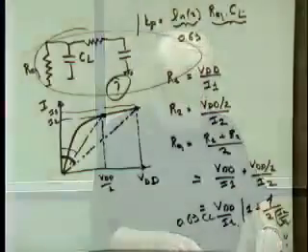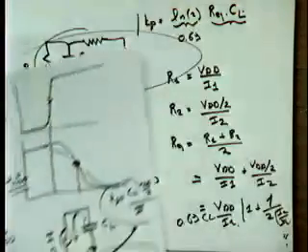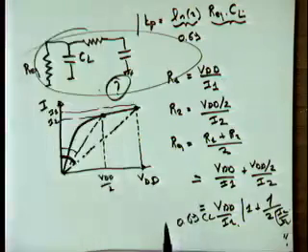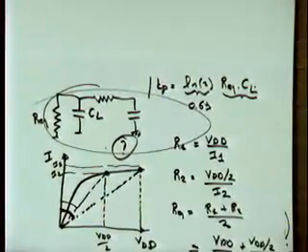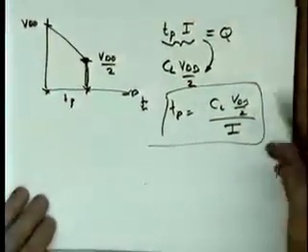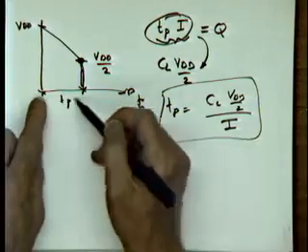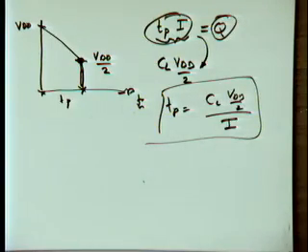On the other diagram, the way you did it the first time, you had Q equals I TP, and then you said that equals CL VDD over 2. Yeah, and then you were explaining it further. So this is the charge that I'm going to remove: if I take a certain time TP with the current source, I take a certain charge Q that I'm going to displace, right? And that charge is going to come from the capacitor.